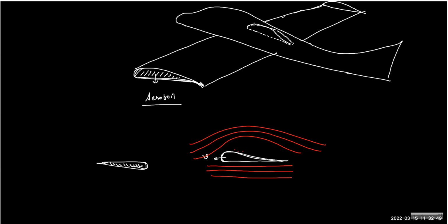So the presence in this location is very less. But we have more air particles here. And because the air particles suddenly decrease, this pressure, which is of course atmospheric, let's say P atmospheric, this will be much less than P atmospheric. And the difference of the pressure will actually create the lift.